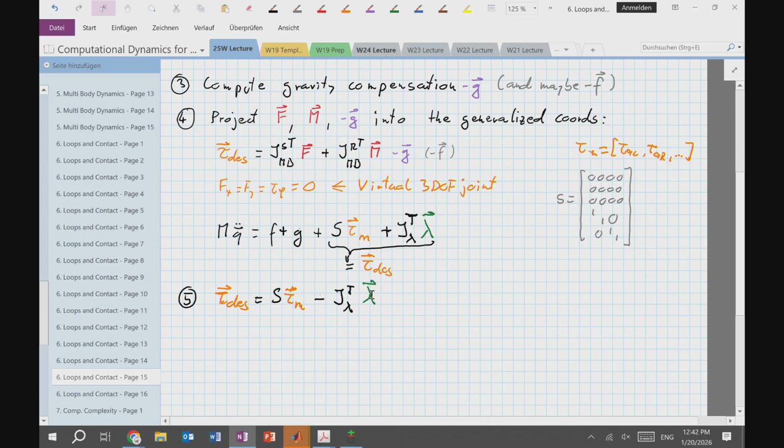If I have 4 here, 2 legs on the ground, then I have 8 unknowns to generate 7 torques, and I should be able to do it, right? These 4 ground contact forces plus my 4 motor torques are able to keep me upright. I can also have a degree of freedom, right? Because I have this extra one. There's 8 on the right, 7 on the left. Where's that extra degree of freedom? You can move up and down. But that basically means using my torque desired, because that means I generate an upward force, right?